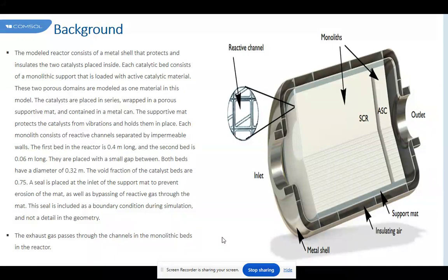When the operation of the reactor is on the ignited branch, it is shown that the monoliths with metallic substrate clearly lead to a superior steady-state performance compared to those with ceramic substrate. In such cases, the ignited branch extends to lower inlet gas temperature, typically between 60 to 100 degrees centigrade in after-treatment applications, for the same catalyst loading.